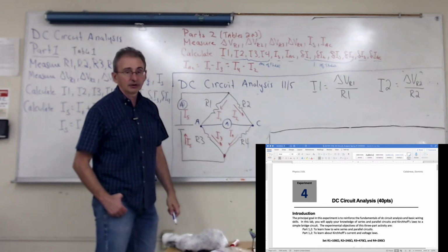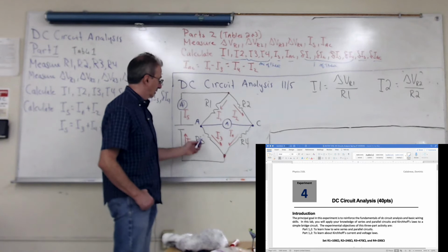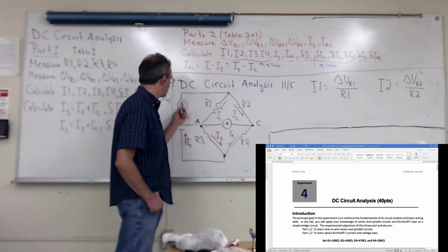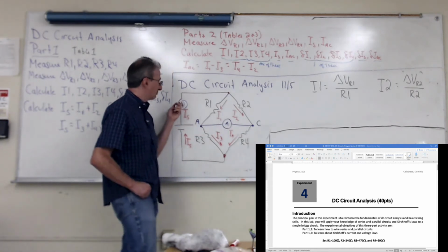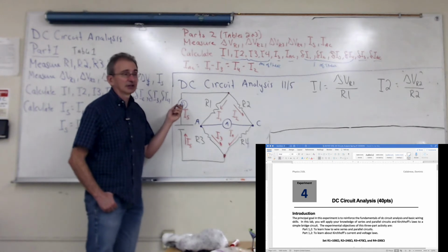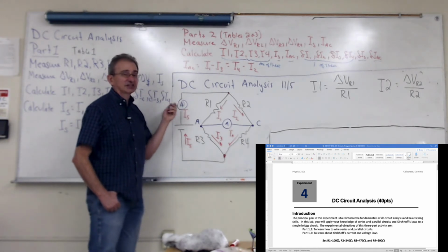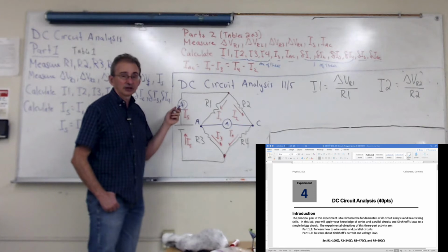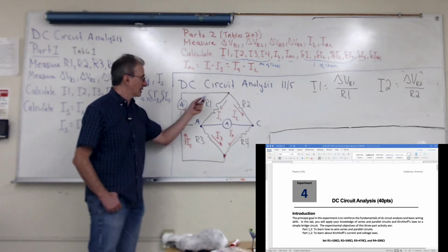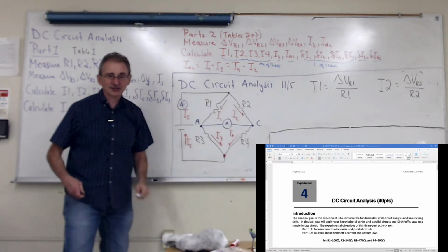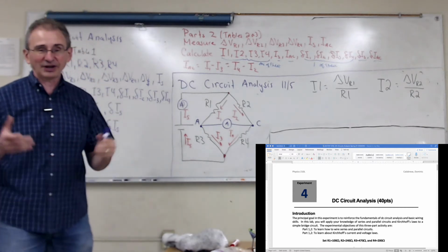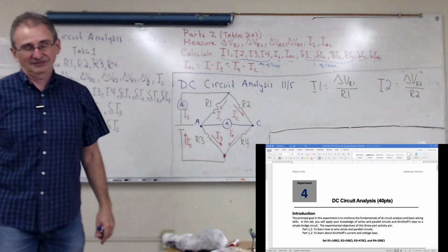That's for part 2? Yes. So this always has to be there. For this ammeter, you're still going to measure I sub S. Once you've measured I sub S, you actually have to take it out of the circuit, because then you have to use that meter to measure all the voltages across all the resistors. Otherwise, you need 3 meters. We didn't give you 3 of them.